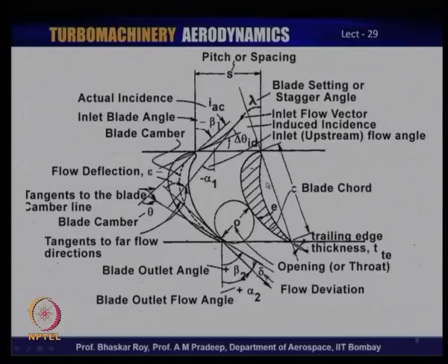It is really necessary for blade fixing and setting of the blade, because the huge camber that turbine design blades normally carry by design actually sets it apart from the chord direction of the chord, and as a result it has really nothing to do with the blade setting angle. But at the end of the day, you have to provide the blade setting angle by design, because the blade will actually be fixed there at the time of assembly.